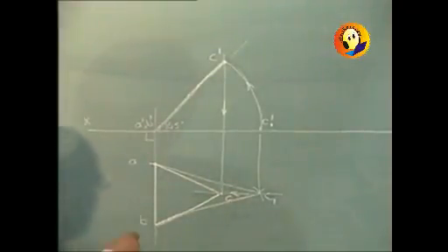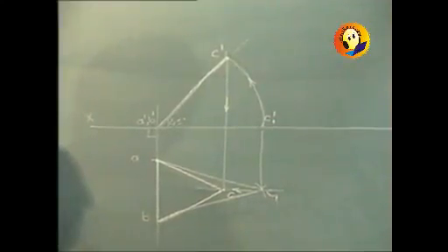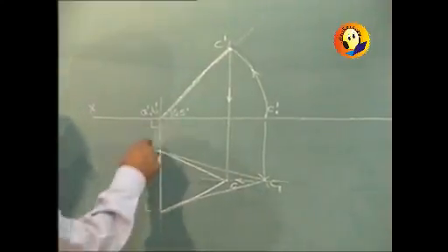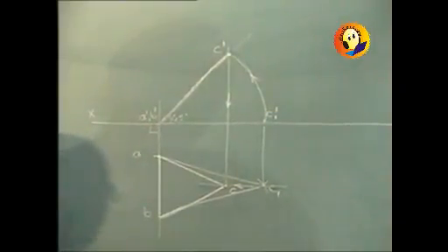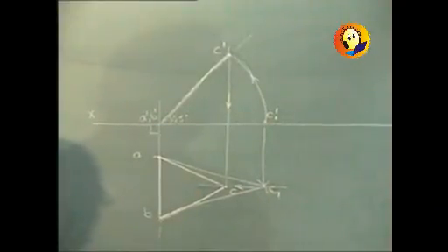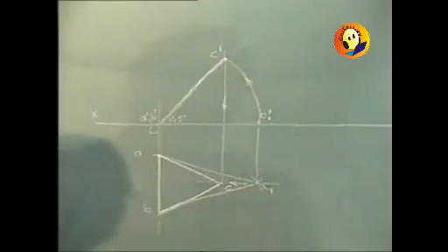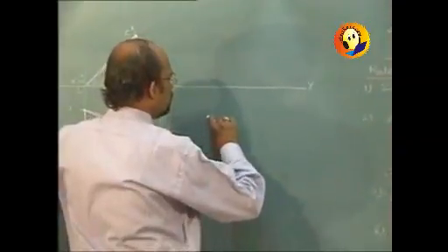It is given that line AB should make 30 degrees with VP. Angle with VP will be seen in plan, but in plan right now AB is making 90 degrees, so we are required to redraw this figure with AB making 30 degrees with VP. So we have actually finalized the shape of the plan over here. Now we will draw a line at 30 degrees.